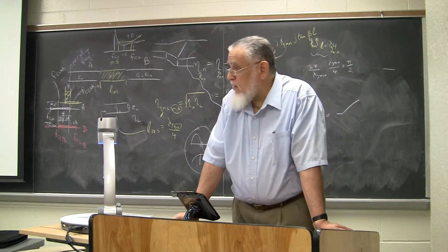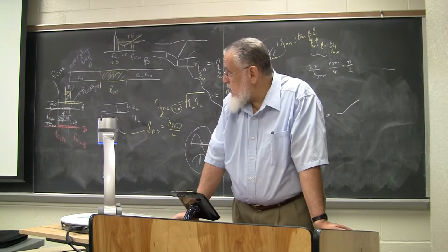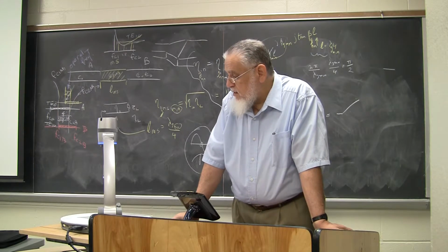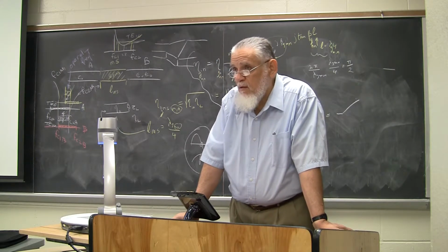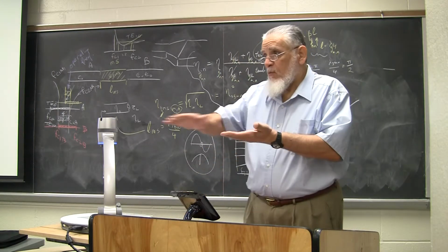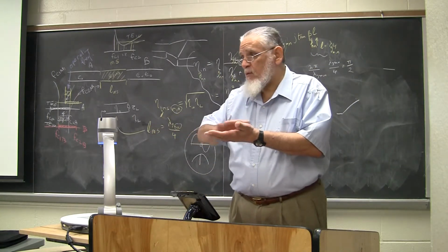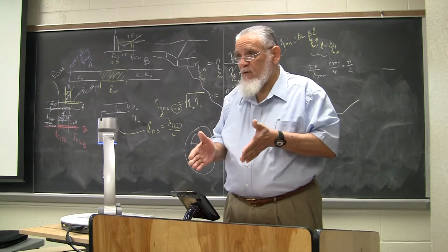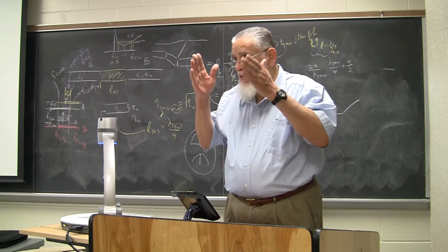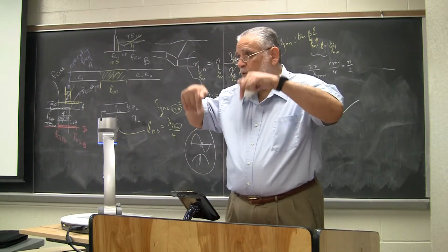The outer shield, as you can see, is from the bottom, the top, and the sides. The side shield is the hardest to make in planar geometry. Usually we work with layered things. We layer things together. Going vertical is hard to achieve, right? So typically the vertical thing happens through what we call vias.